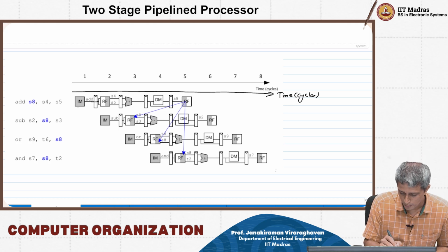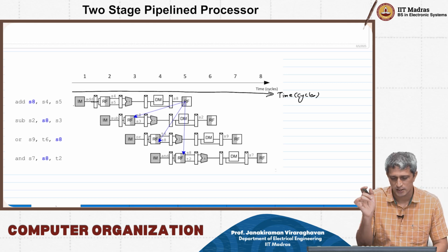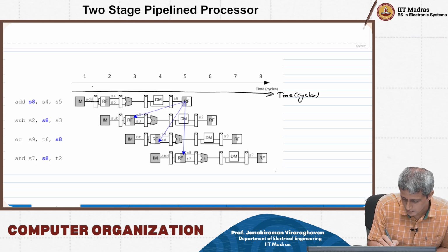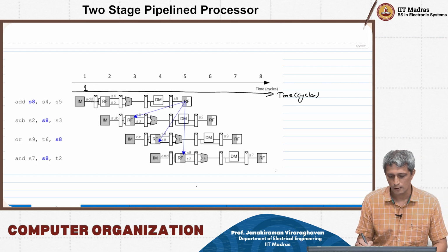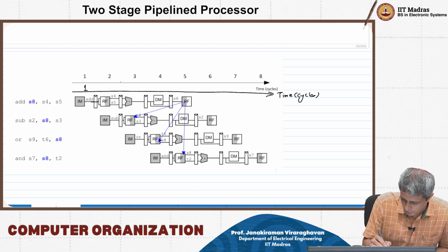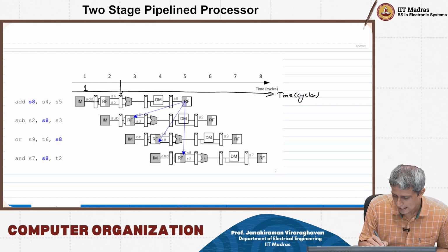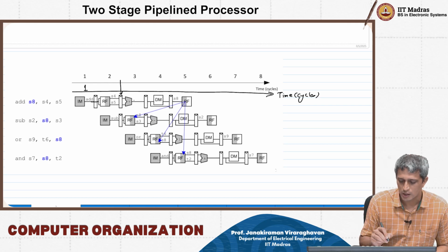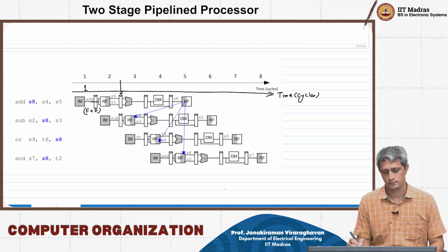So if you look at it, my instruction fetch and register file is basically the first clock cycle that we are talking about, right? This is my first clock cycle. This flip-flop, right, is the only flip-flop that is going to register my data, and then I have so this is my fetch plus decode operation.